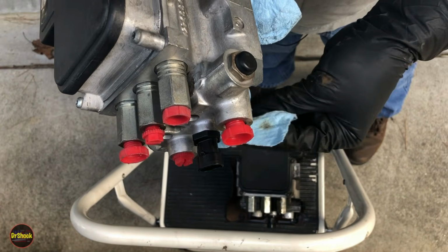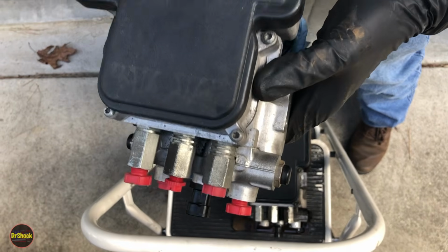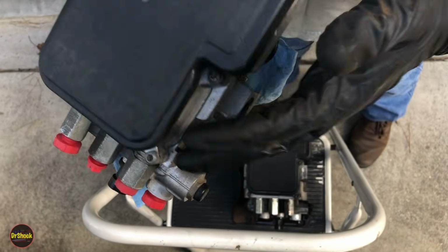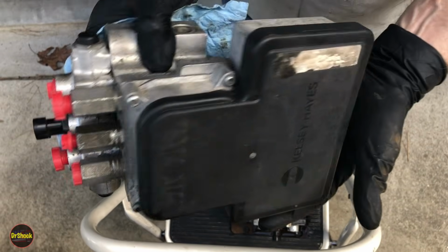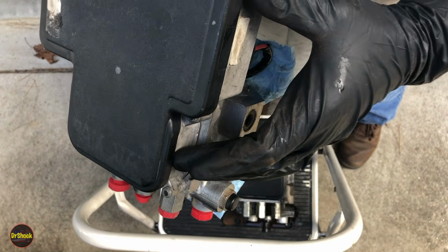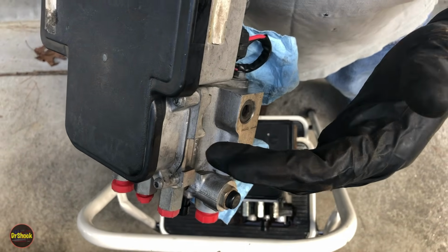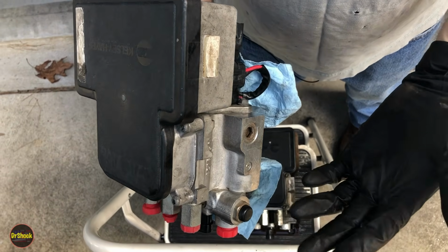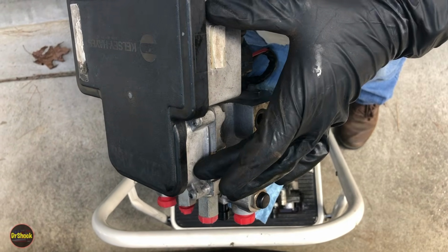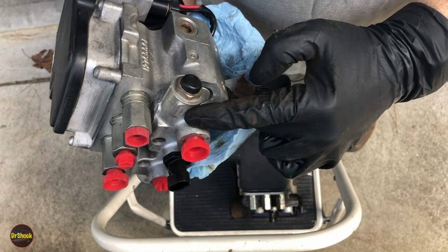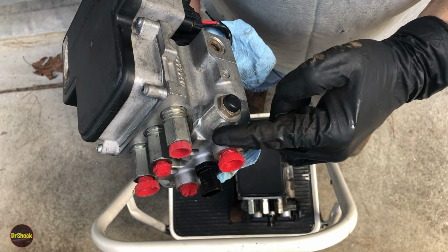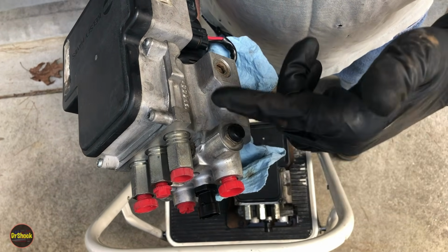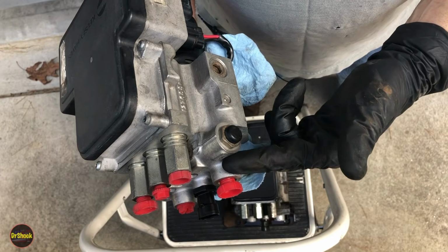And the reason I'm going to take it apart and talk to you about it is they're not the same. They look the same on different trucks, and the EBCM has no identification marks on it whatsoever. But they're different depending on whether you've got JB5 or JB6 or JB7 or JD7 or JD8. Different kind of brakes take different EBCMs and take different proportioning valves. Also, if you have a G van, there's some differences. A P van, there's some differences. So I'll go over CK trucks, P vans, and G vans, and also go over S and T trucks in just a minute.